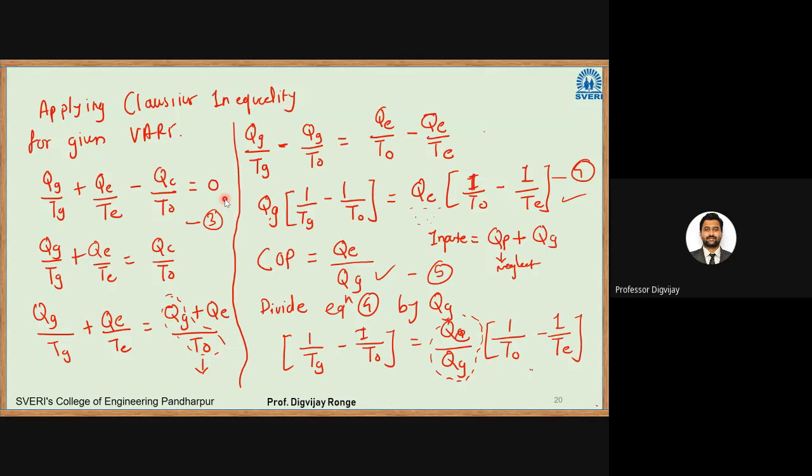Okay. In the irreversible case, what is our equation? dS is equal to the integration of dQ/T plus entropy of generation. So the entropy generation is always greater than or equal to 0. Entropy of generation is 0 for only reversible processes, and entropy of generation is always greater than 0 in case of irreversible processes. So that is why you might remember the statement that entropy in the universe always increases. Okay.